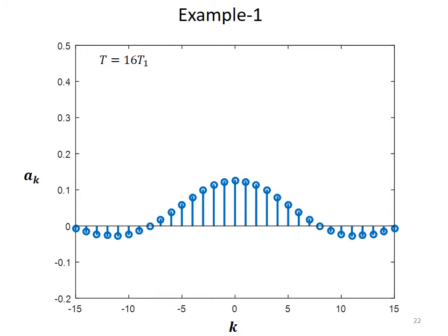So when duty cycle is higher, the power can be found in DC and the fundamental frequency component, right? And when duty cycle is reduced, you can see the power is being distributed among all the frequency components, or in other words, other harmonics are getting stronger, and the fundamental frequency component and the DC component are actually getting weaker.